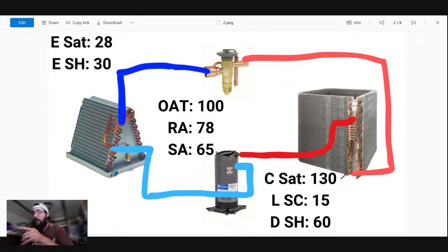Let's see. I think either liquid line restriction or oil plug, TXV failed, or superheat spring wound up too much, or low charge, non-condensables. Maybe TXV screen plugged.